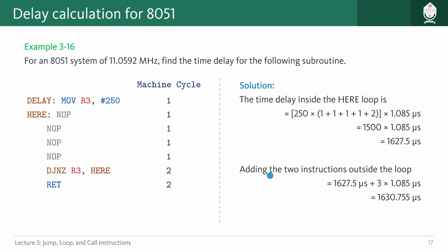We just have to understand the concept, which will be done through this basic 8051 system, where we have 12 clock pulses per 1 machine cycle. Basically we are talking about models like the 8051 or 8052 systems, where 12 clock pulses equal 1 machine cycle. All of the problems we will give in the exam will be based on this one.